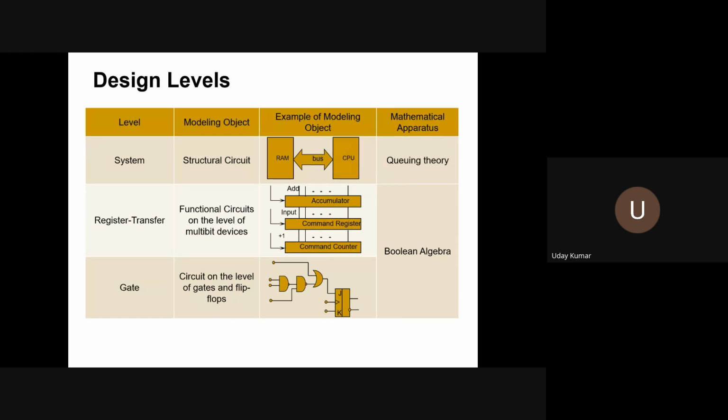If you increase the bus width, it might not even pinch you a bit while you're doing the front end design. But in the back end, when you go to routing, it will be very complex and tedious for the engineers to perform routing with that much bus width. It occupies a lot of metal resources. We'll be discussing that later.